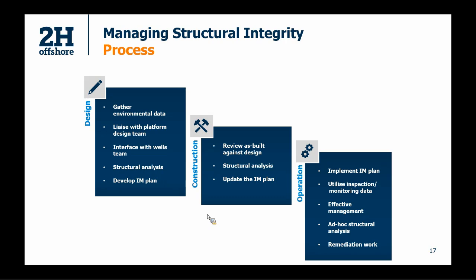And then the most important thing is, through operation, to actually be implementing that IM plan. It's also useful to utilize inspection and monitoring data. A lot of the time the inspections are carried out, but not a lot is done with the data. If you can take wall thickness measurements or corrosion images, and you can see that it's increasing at a rate quicker than you would have expected, then it's useful to know that in advance, rather than finding out 10 years down the line, once the corrosion is too significant, that you're then looking at a much more significant problem.